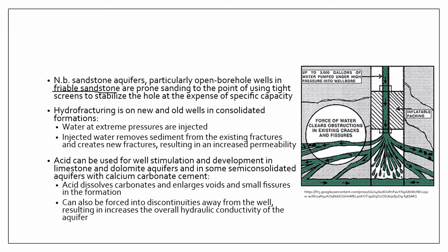They can actually collapse, right? Or undergo sanding. So typically the preferable method here is to actually use small sized screens to ensure the stability of the hole, even if it actually reduces the specific capacity of your well.